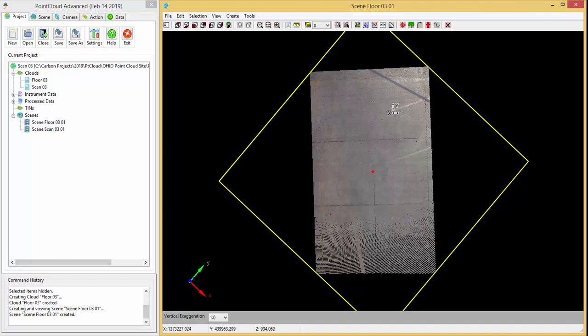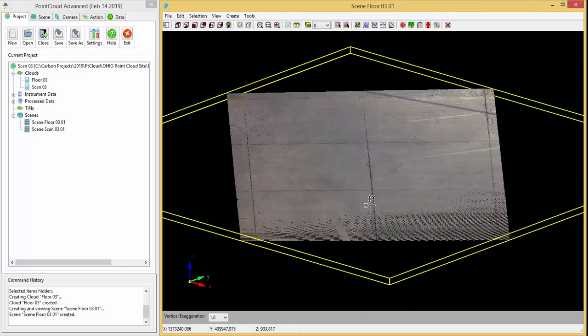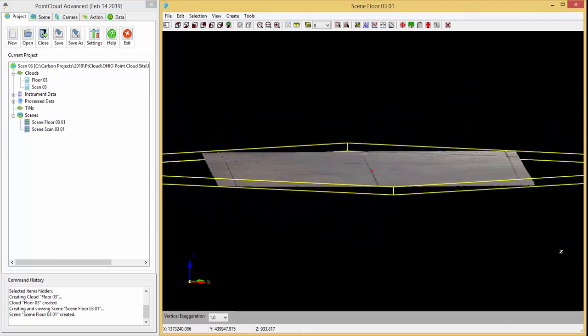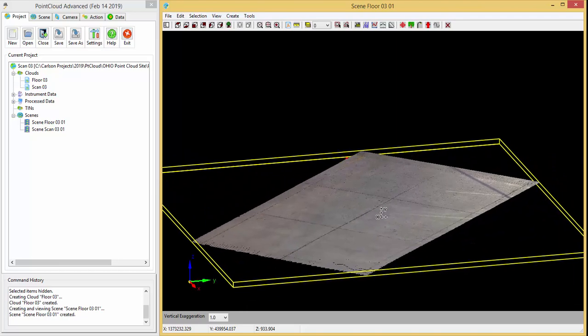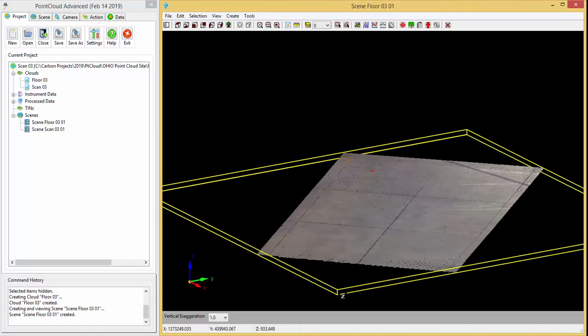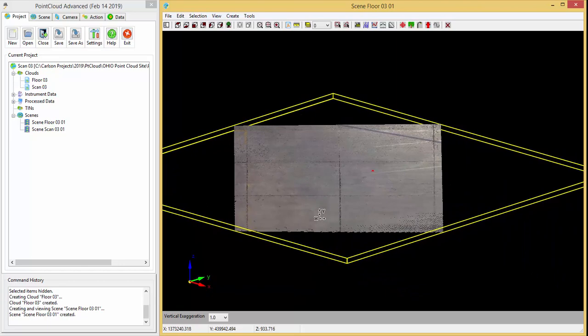Alright, so we're going to want to know what is above and below the flat plane of 934. Now, when you look at your site, because I have one scan, I won't have much sponginess, I call it, or thickness. When you have multiple scans registered, sometimes you can get a little more sponginess, where points might be a couple eighths of an inch or 16th of an inch below another surface just because of the way it was registered. So I've only brought in one scan for these 6 tiles here for the concrete floor.